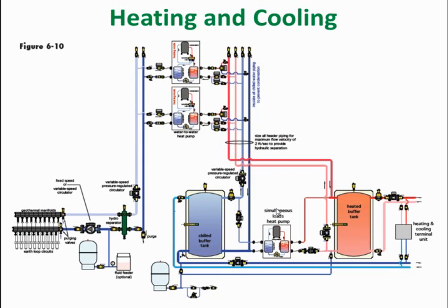So basically, and I'm going to read this right out of Hydronics 9 because it is a little bit complicated. The COP of the simultaneous load heat pump would be the ratio of the total desirable heat transfer effect divided by the total electrical input. So in other words, if that heat pump down there in the center is on a 30 amp breaker, that would be the electrical input. We give you a formula for calculating that COP when you put it in a simultaneous system like that.